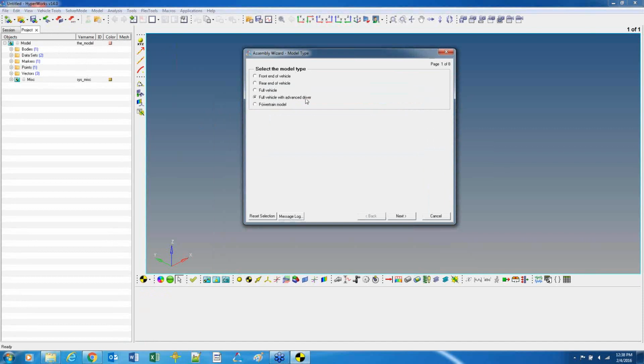Now this driver allows you to, instead of just defining one event like drive straight for this long or do a turn at this time, actually access something called the Altair driver file, which I'll show you in a minute. And this is really free form. It lets you do things like run for 2 seconds. And then at that point, whatever the state of the vehicle is, I want you to do a sharp turn. And then maybe you do that for 4 seconds, and then you want to do a sharp turn back.